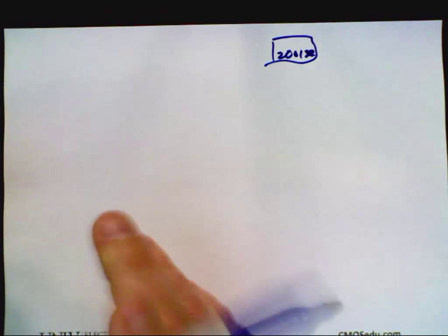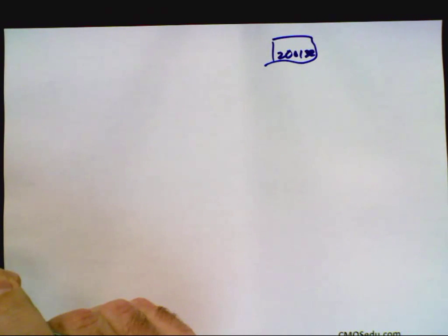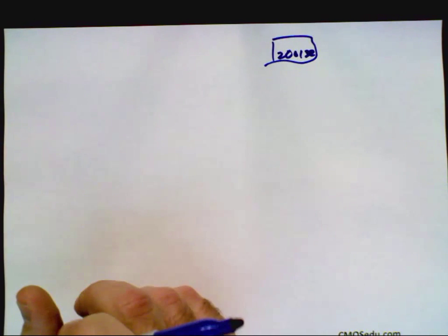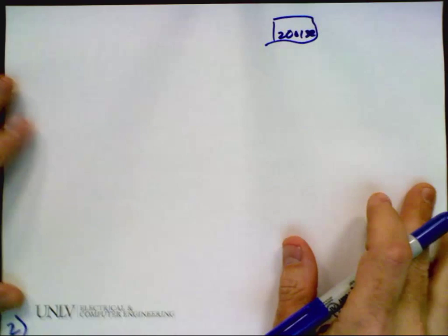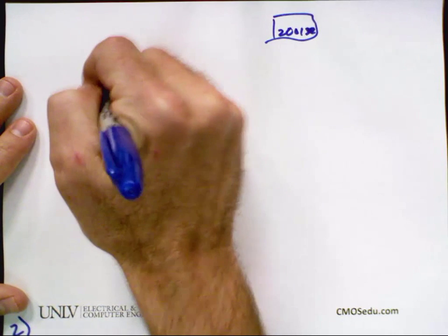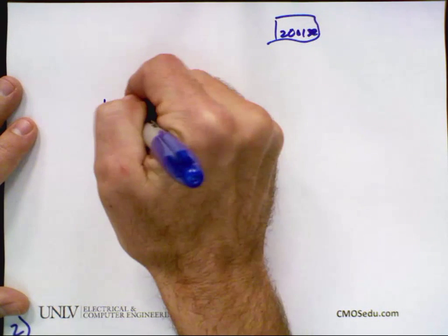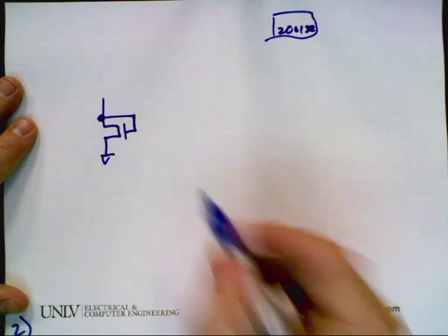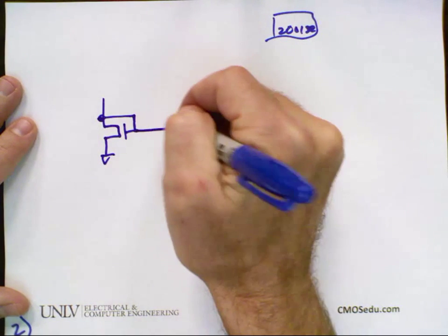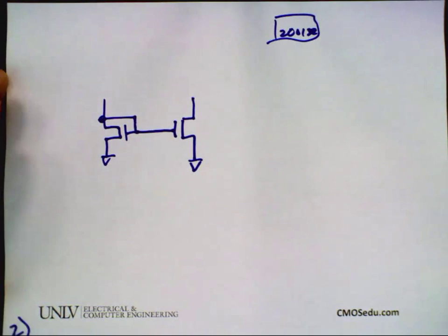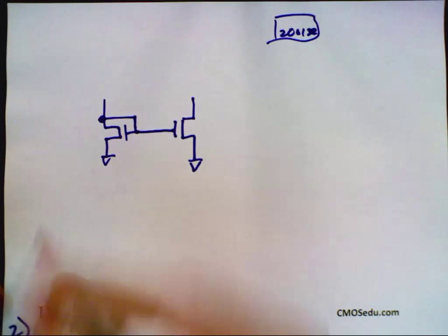Because I remember back in the day I tried to make an op-amp using discrete transistors, and it didn't work very well. So I just want to keep that in mind. So if you try to do power MOSFET current mirrors or something, it may not work. Okay, so a basic current mirror looks like the following. And we're going to go over the operation here real quick, because I want to point out some real key points. In all of these topologies that we talk about, what we care about is the VGS.